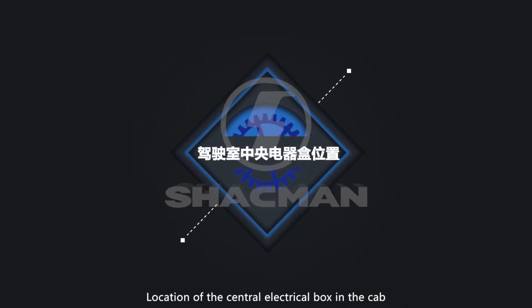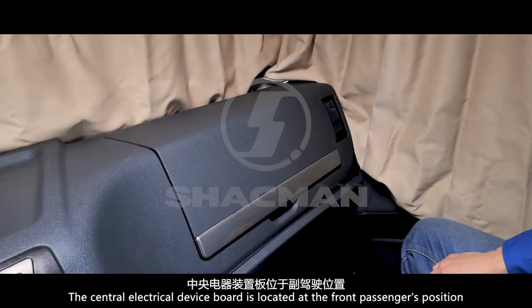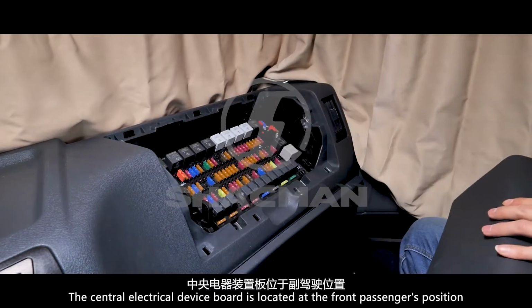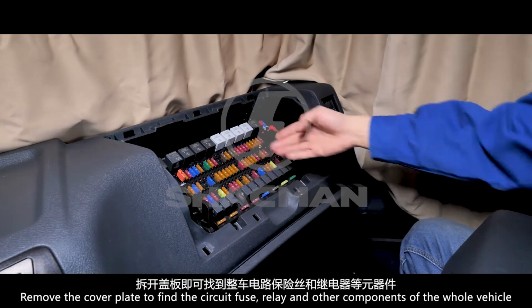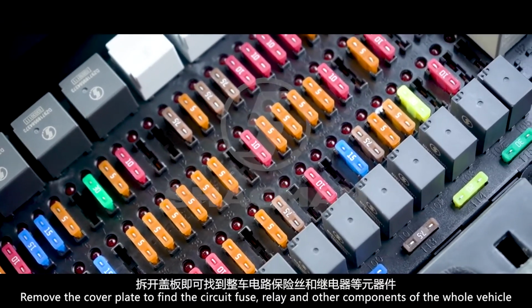Location of the central electrical box in the cab. The central electrical device board is located at the front passenger's position. Remove the cover plate to find the circuit fuse, relay, and other components of the whole vehicle.